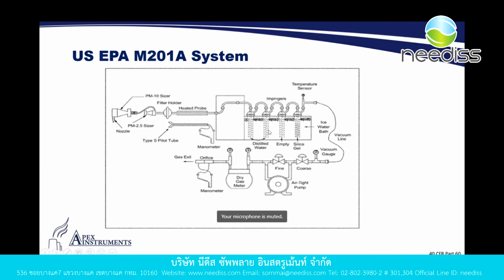your second impinger having 100 ml of distilled water, your third impinger being empty, and highly recommended by us is the last one having silica gel to do a final moisture removal and removing any acid gases that may be remaining in the sample gas, in a last attempt to make sure we have a dry and clean sample gas exiting the last impinger, so we are protecting our dry gas meter in the console for longevity.